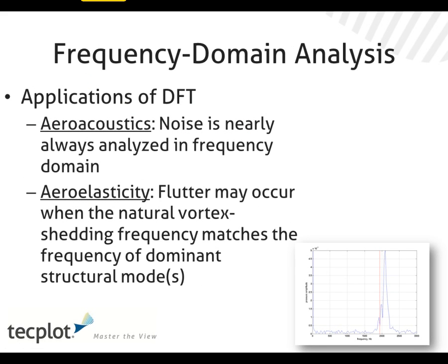Oh, yes, we mentioned frequency domain analysis. And here we have now in Tecplot a discrete Fourier transform capability, so you can actually look at the results in the frequency domain, so you can get an idea of where your dominant frequencies are and harmonics. That's useful certainly in aeroacoustics, where generally you want to look at your frequency versus some sort of amplitude.